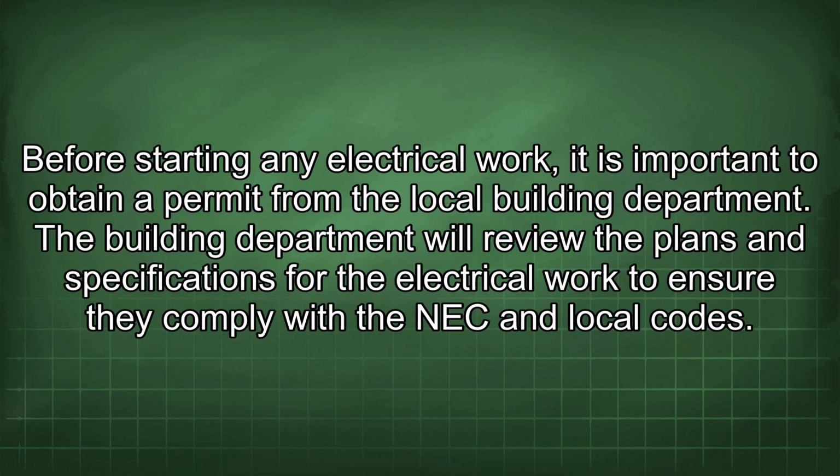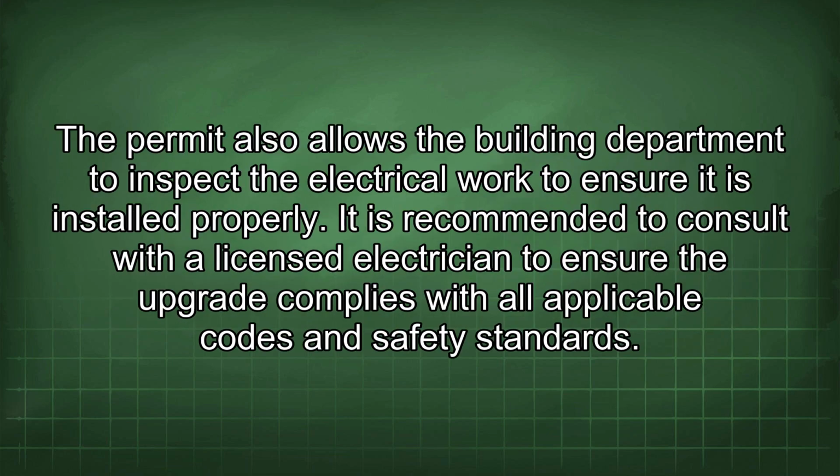Before starting any electrical work, it is important to obtain a permit from the local building department. The building department will review the plans and specifications for the electrical work to ensure they comply with the NEC and local codes. The permit also allows the building department to inspect the electrical work to ensure it is installed properly.